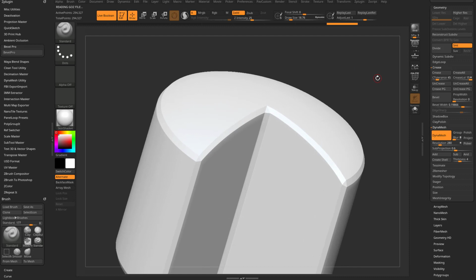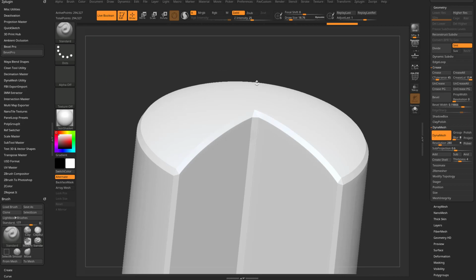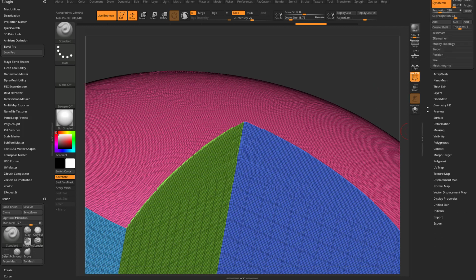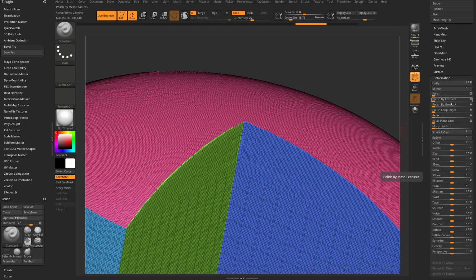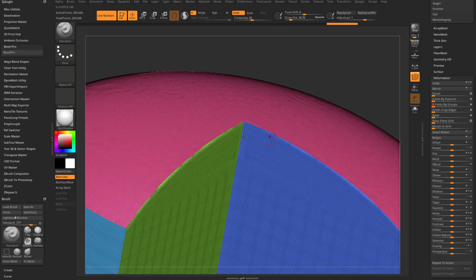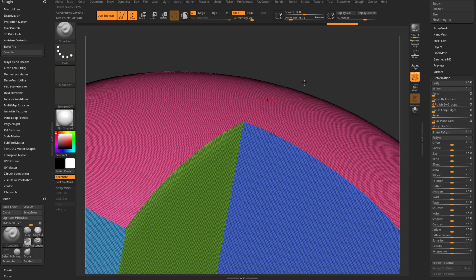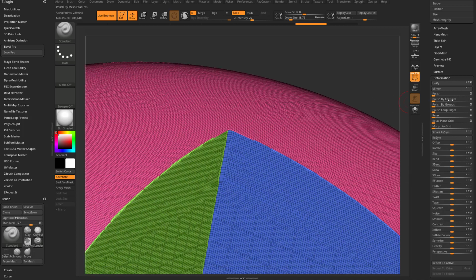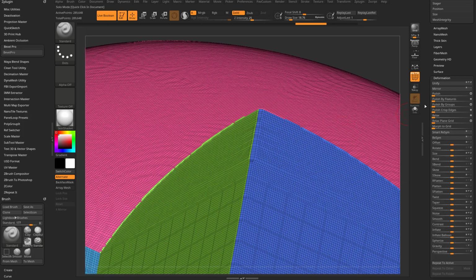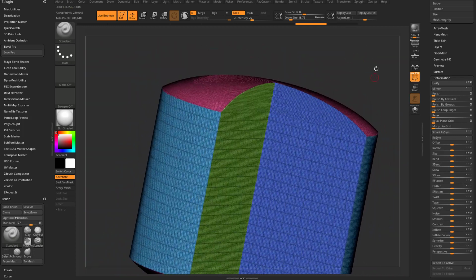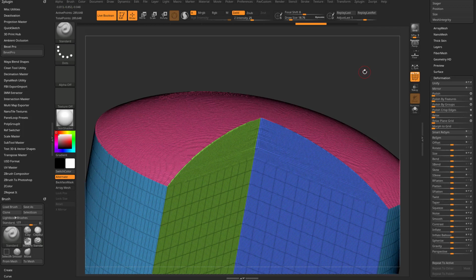So again, even though it was nasty Dynamesh geometry, we were still able to use Bevel Pro and get out of some nasty situations with smoothing by groups. And if I can show you the manual way, basically what it's doing is you can go down here, deformation, you have polish by groups right here, so you can just crank that up and that'll go ahead and again polish your polygroup border. You can do closed circle to maintain your volumes. You can do open circle to really polish the heck out of your object here. So you could do it manually if you'd like. And in fact, polish by features, a feature is basically a polygroup border or a crease. So either one, you can polish by features to smooth this up as well before you head in, but it's also built into Bevel Pro, so you can have it handle it for you.